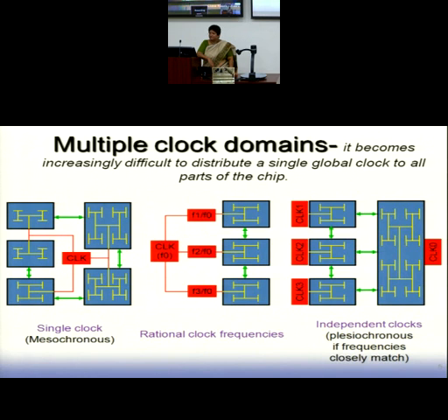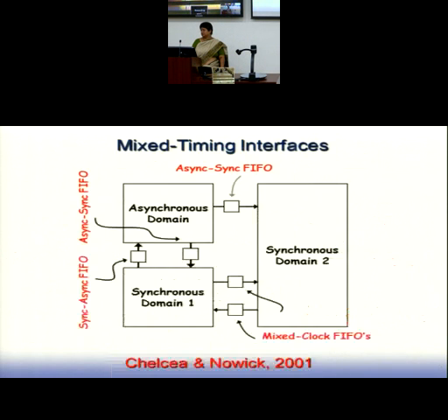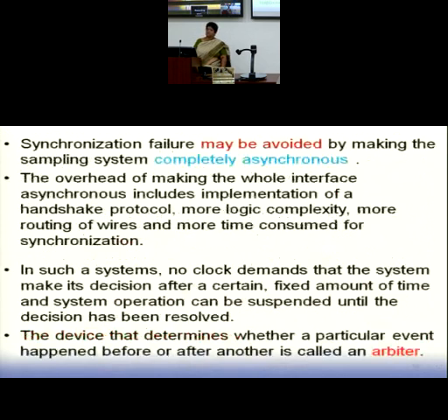So a synchronization error is less of a problem than a synchronization failure, because once the system goes into failure, it takes time to come out of it, which we do not want. Whereas such a thing doesn't happen here. The only thing we need to do is re-input our value because an error is reported, and then the output would be corrected. Nobody knew about it till the 1970s, when a thorough study was made, and metastability was found to be causing systems to fail.